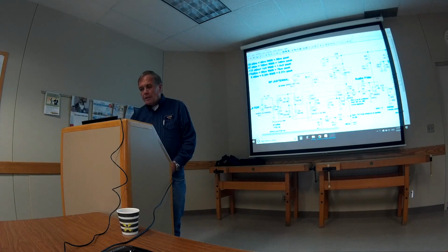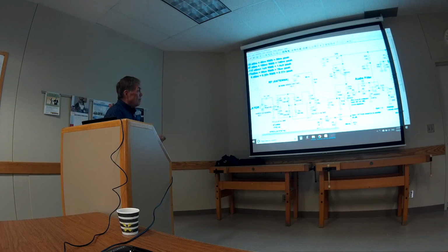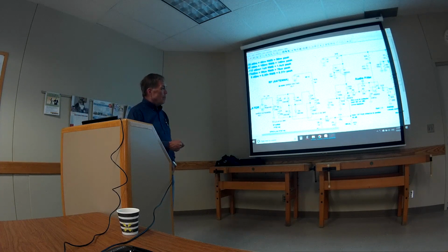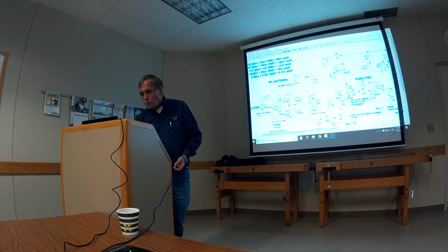So this is kind of stepping up the impedance and stepping down the impedance, or the other way around, to match. The antenna comes in one of them, the local oscillator goes into another one, and out comes audio. It mixes it very nicely. But down here you have to do some playing around, you have to terminate it. You have a diplexer, they call it, to get rid of some of the unwanted signals again. And then it comes on up to a little amplifier here.